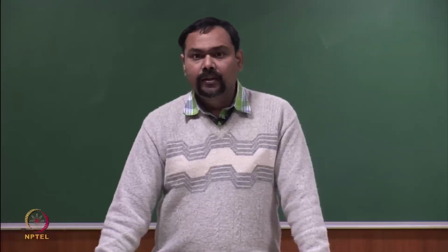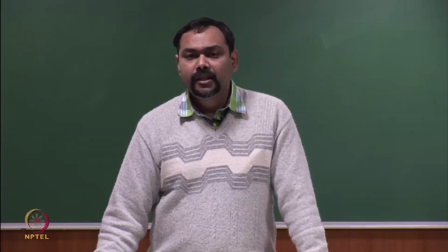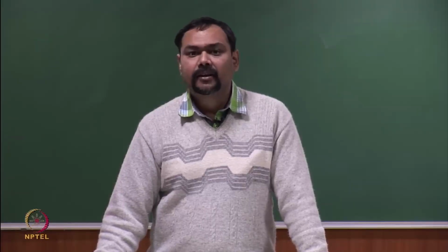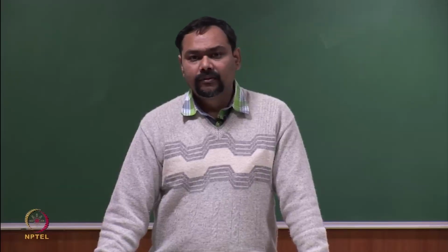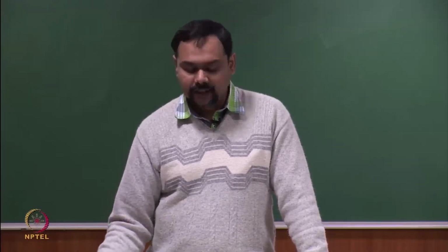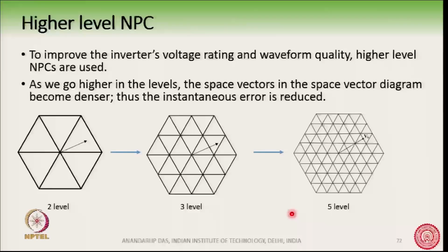Now, if you go with a 5 level NPC, if you see the space vector diagram, then you can immediately see what is the advantage of having a 5 level space vector diagram or a 5 level NPC. You can see here in the diagram, you have a space vector diagram for a 2 level converter, for a 3 level converter and for a 5 level converter. And you can see that in a 5 level converter, the space vectors in the space vector diagram are getting closer and closer to each other, they are becoming more dense.